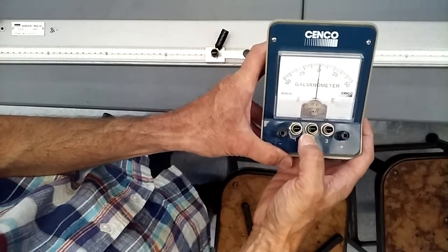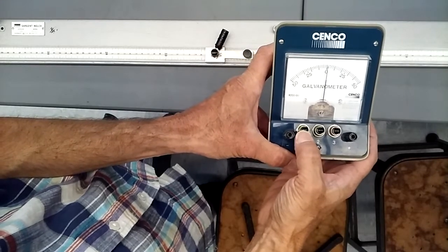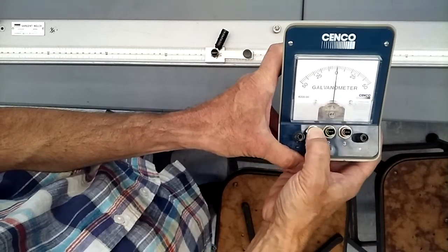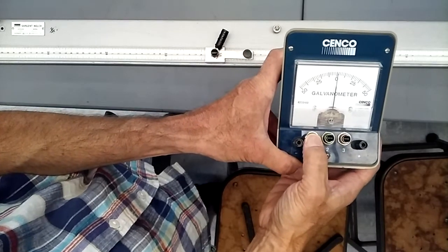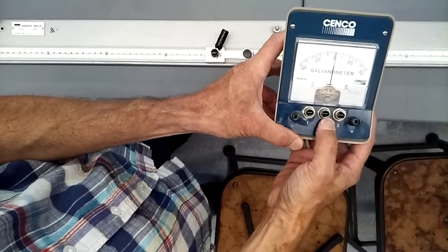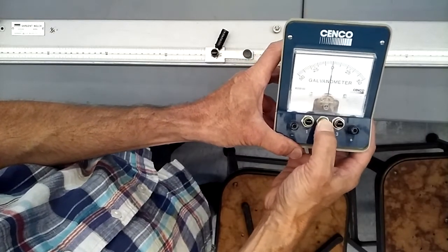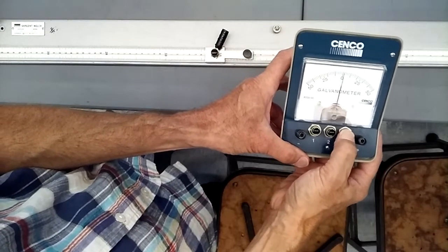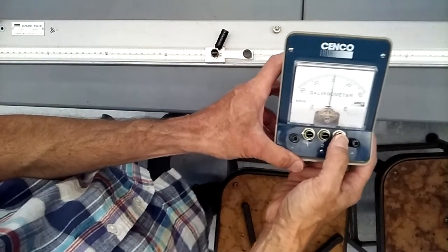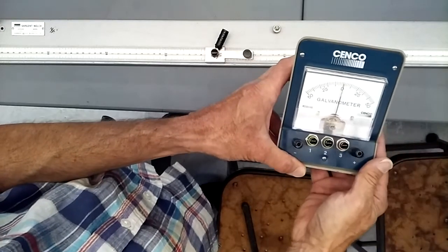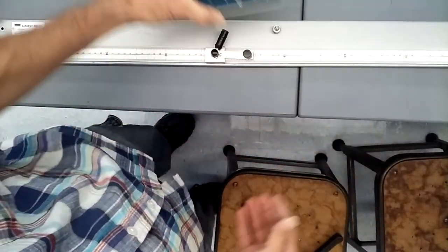And so you aren't really going to have to make numerical measurements. It's a matter of just looking for when current is zero. The first key measures to a coarse degree, and then the next key measures to a finer precision, and then the last one, number 3, measures to the finest precision. So you just kind of work your way through while you're varying the position of the slide wire, okay?